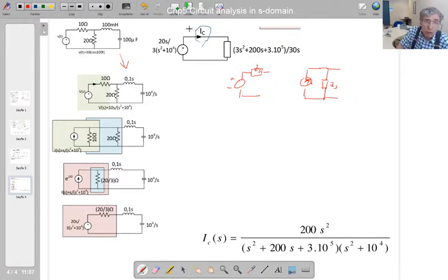According to passive sign convention, the current of these independent voltage sources is downwards, but the current of the independent current source here is upwards. So you could use the source transformation by paying attention to those references that have been taken into account here. Replace this green shaded circuit with that green shaded circuit, which includes the independent current source of which current is upwards, like that here.